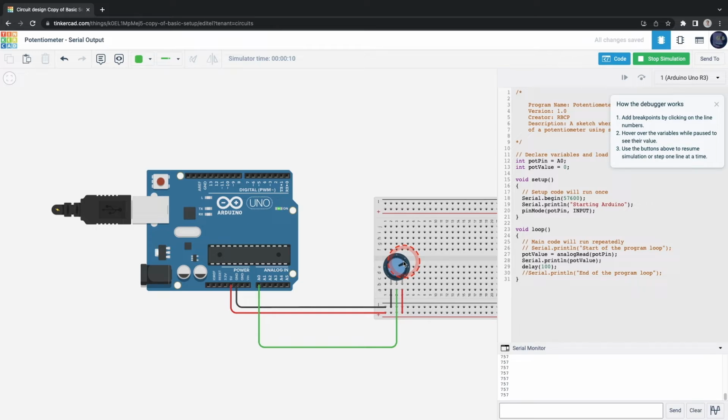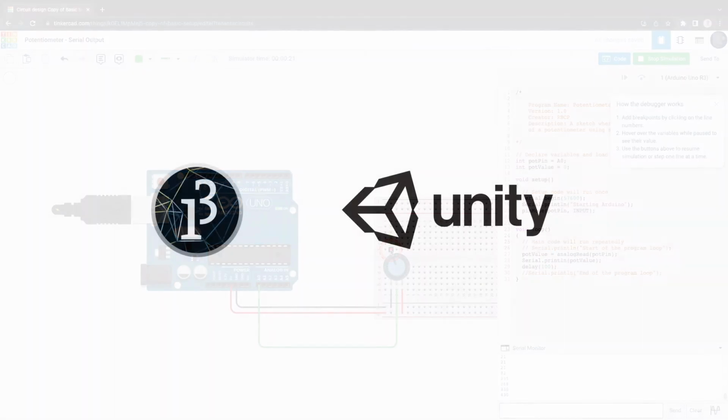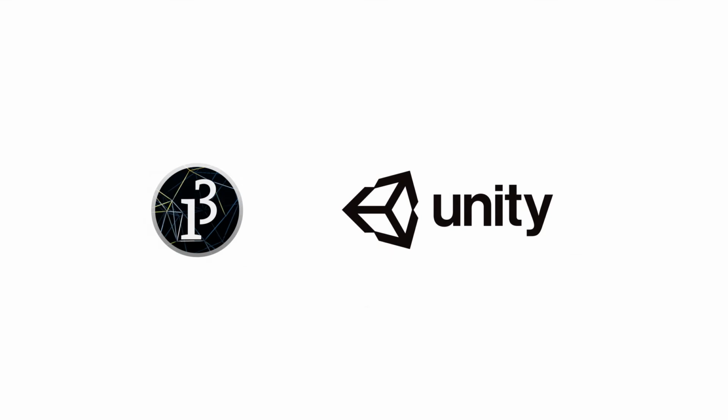If you recall, every time we used serial.println, we are sending serial information. We are able to read this information using the serial monitor. Our goal is to read the information from other programs, like Node-RED. I should also note that you can use other programs, like Processing or Unity, to read serial information. So that means we can connect the Arduino to all sorts of different pieces of software.